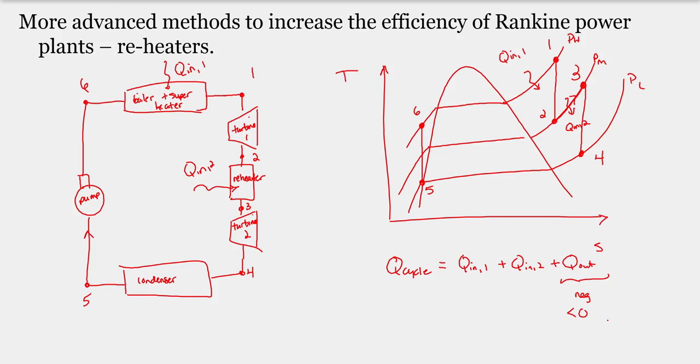that have more complex heat exchangers. Now, I drew this as a system that occurs in series so that we could see it very, very clearly. In reality, there aren't 2 turbines. There are staged turbines. So this would actually be a 2-stage turbine where we're withdrawing some fluid to go through the reheater, and then it expands through the second stage of the turbine. Okay, so again, this is drawn for simplicity. In reality, there aren't these distinct components. They're very much more compact.